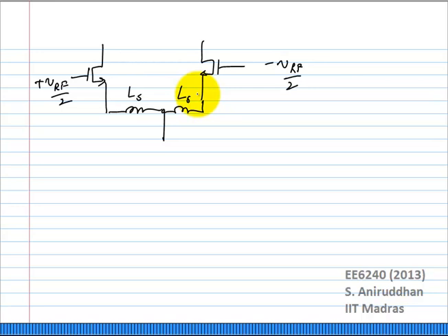So, suppose I have these unwanted frequencies at which I want to reject the gain of this circuit. There happens to be an easy way to do this, which is by adding a parallel resonant circuit in series with these with the ground connection.